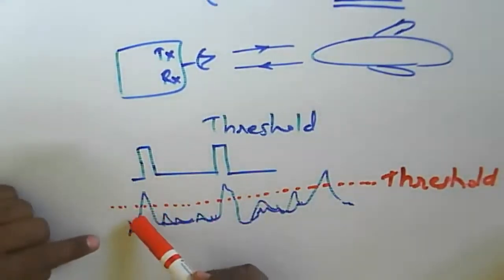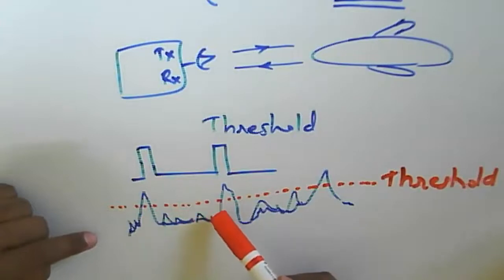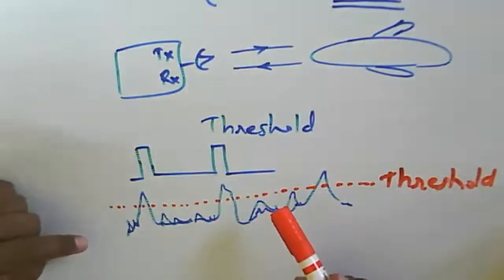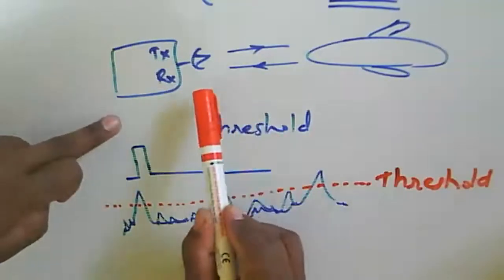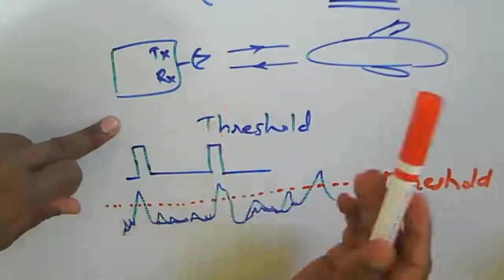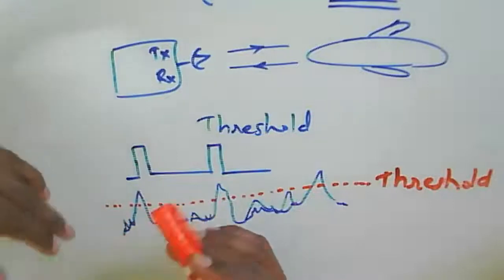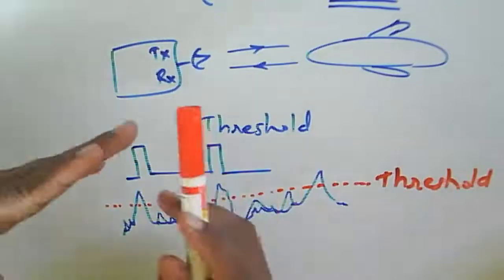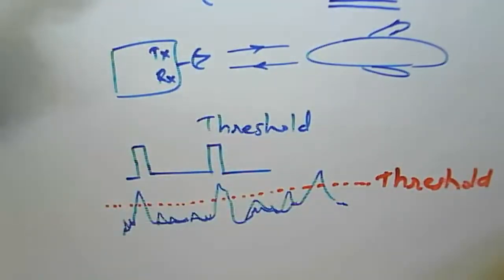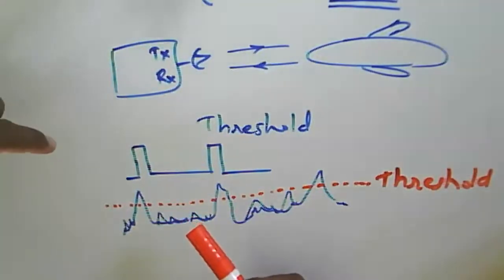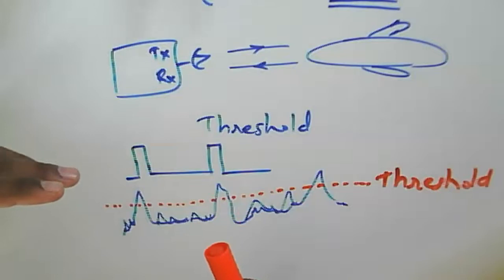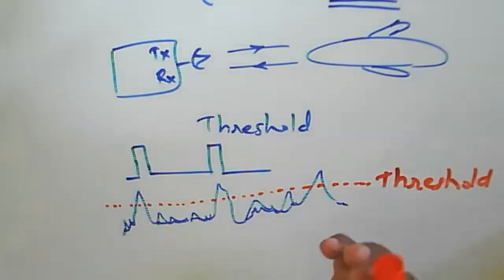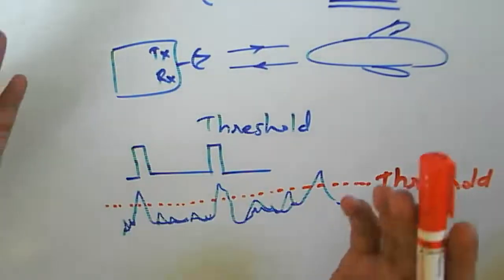Because this pulse has some particular noise, and that noise does not come from the echo signal or externally, because we have a noise filter earlier, and after that we use an IF and then a matched filter, and the IF signal is passing through this. So this noise occurs at the receiver. At the receiver means what? Generally, we say that a receiver is detecting the signal, and then what happens at the receiver?